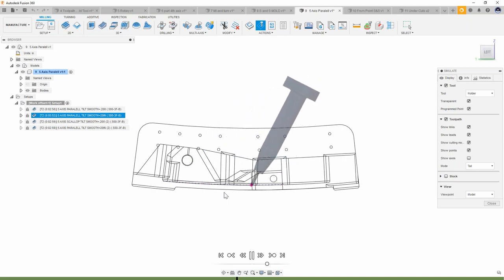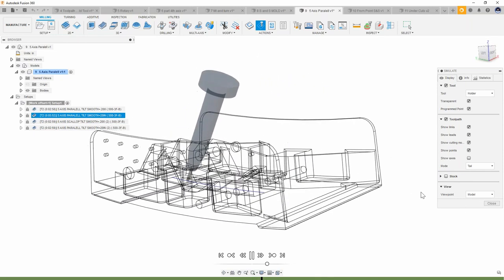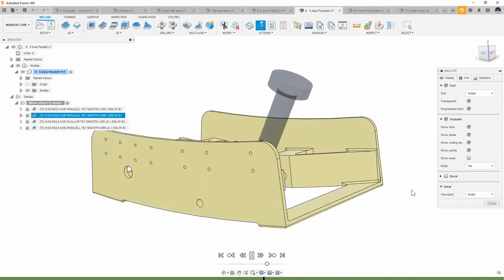Which is my desired result, because I don't want it to be 5-axis the whole time if it doesn't need to, and it's obviously going to run faster this way if I can do the 60% of the toolpath in the middle from a fixed location. So this is where making just a vertical toolpath into 5-axis becomes really beneficial, because this is what it's doing, and it's correcting the origin even from our z-axis to get a valid solution. So we don't have to do anything, just check a box, and this makes it for us.